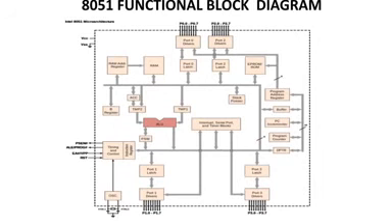This circuit generates the basic timing clock signal for the operation of the circuit using a crystal oscillator. This oscillator circuit generates a train of pulses at the frequency of the crystal. In this, the machine cycle is a group of 6 states. A state is a basic time period for the microcontroller to fetch an opcode, decode an opcode, and execute an opcode. So these 6 states are the basic time period of a microcontroller. To do what it does in that time period,